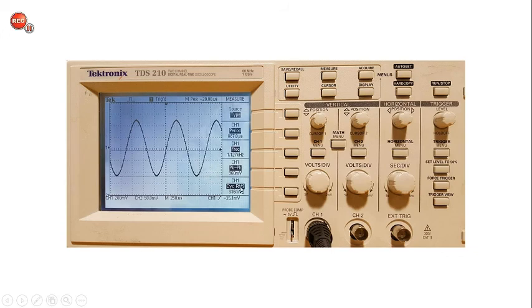And you can see the on-screen menus here. It says that the peak-to-peak voltage is about 960. So my estimate in counting the number of divisions was slightly off, but that doesn't matter because the oscilloscope actually tells me the peak-to-peak voltage is 960 millivolts. I could divide this by 2 and get the peak voltage as well.